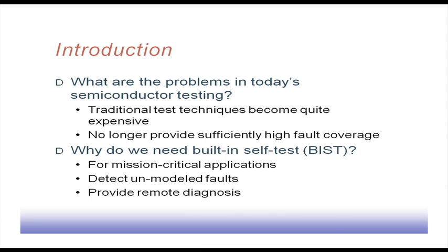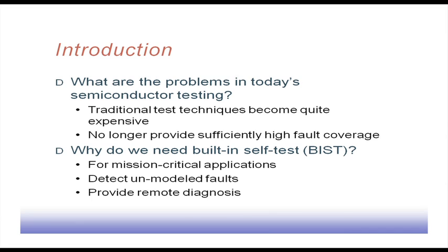If you try out some random patterns, you will not get good fault coverage. If you try a dedicated test pattern generation algorithm, then also it is costly because of the test generation process. And of course, test application is another issue, like the automatic test equipment that we have. The cost of the system is going to be high with the increasing memory requirement and the number of pins that the ATE channel will have. So we need some cheaper solution if we are trying to reduce the system cost.